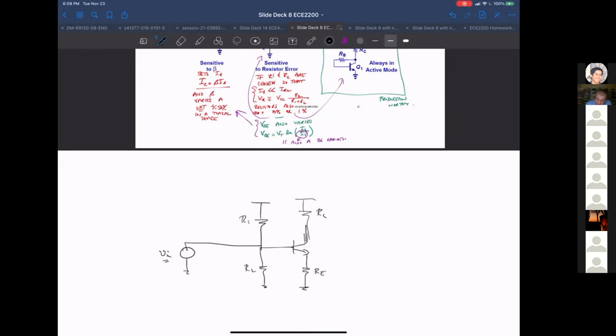Let's say this is our 10 millivolt, 20 millivolt variation, the input we're actually going to amplify. But if I put a voltage source into this input, I would probably screw up the biasing. You basically don't want the DC value of this thing to affect this point. We're only interested in the AC variations in VN.